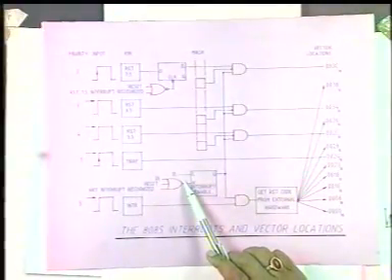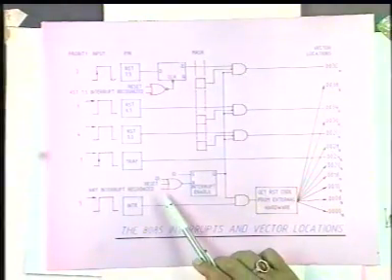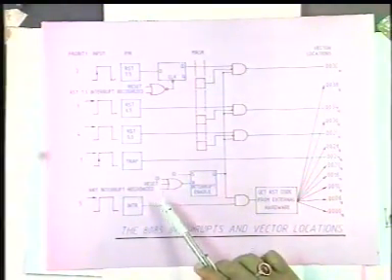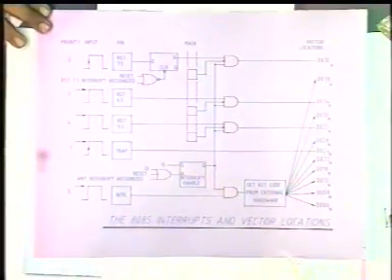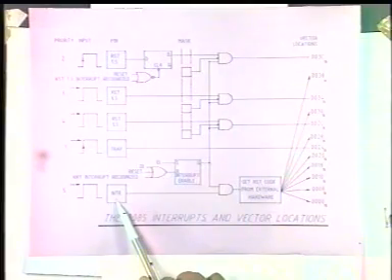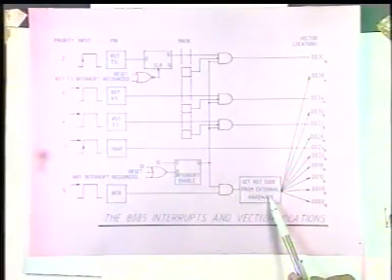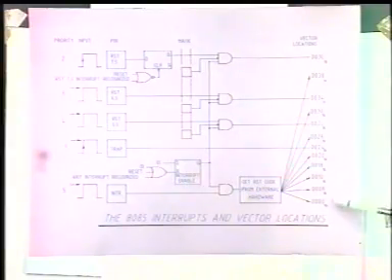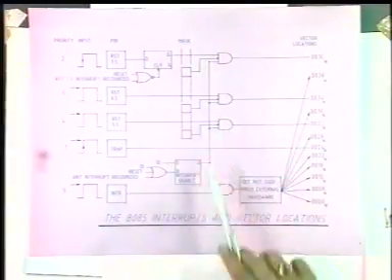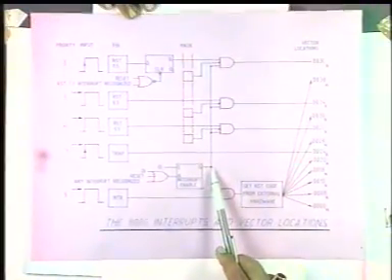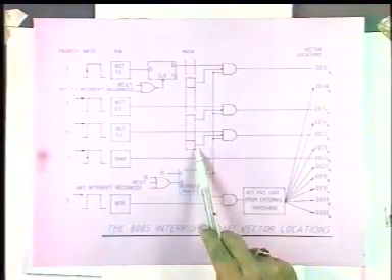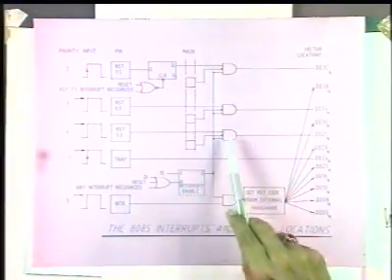that I have a flip-flop which is basically called the interrupt enable flip-flop. This gets set when you execute an interrupt enable instruction, and then it gets reset when you disable the interrupt or when any interrupt is acknowledged. Now, so far as the interrupt is concerned, it has to provide the vector addresses as mentioned here, and this set of AND gates, what you see, is basically enabled by the interrupt enable flip-flop. That means if this is on, then only the corresponding flip-flops will be energized.